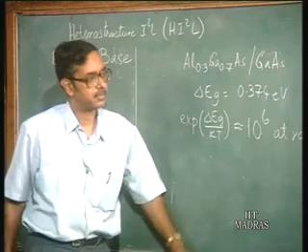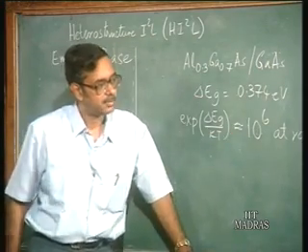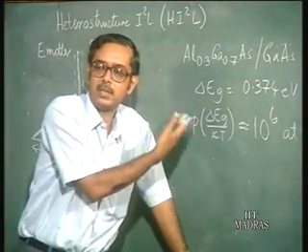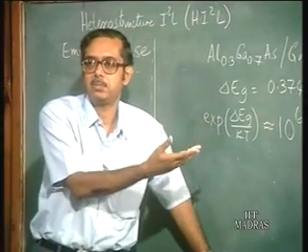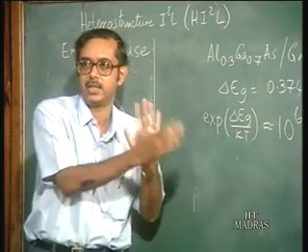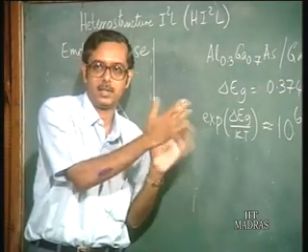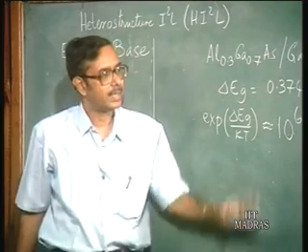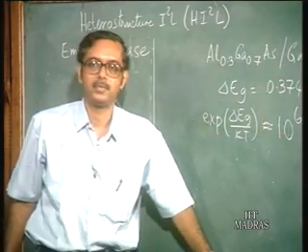In fact, you cannot really have such high betas, because once this ratio becomes so large, beta will no longer be determined by this. Basically, what we have been talking of is emitter efficiency. Beta will be determined by the other factor, that is the base transport factor, the recombination in the base. So it is no longer advantageous to have such a high value of this factor.